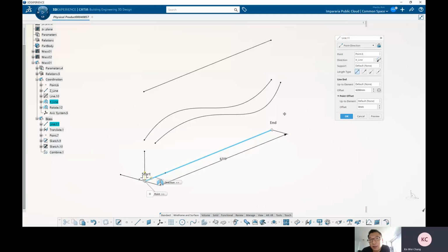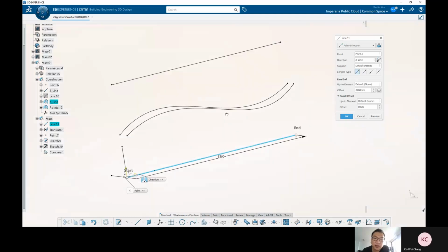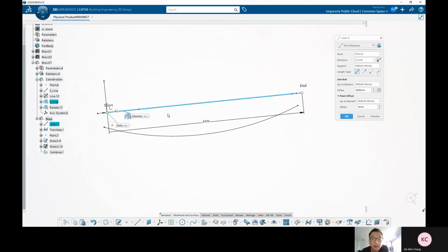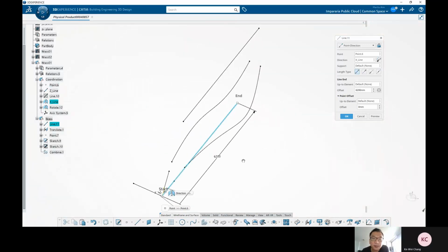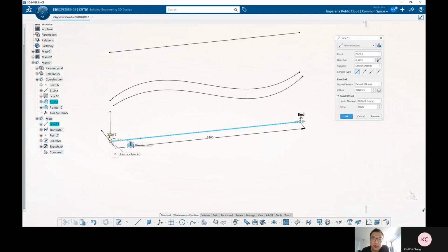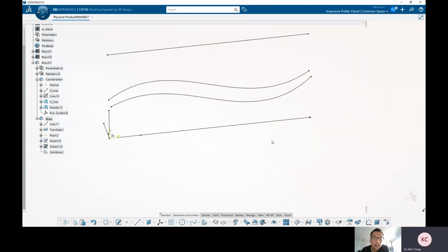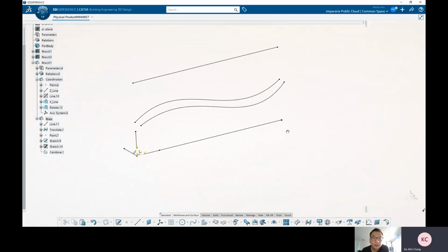It's not because we're going to make an output, but we're going to build the structure. So, for example, this line is controlled by the facade line and controlled by the plan line. So you can control both at the same time. And you see here, when the line changes, this point is always following. So the actual length doesn't matter. How to build is important. Length can always be changed later on. That's the essence of CATIA.